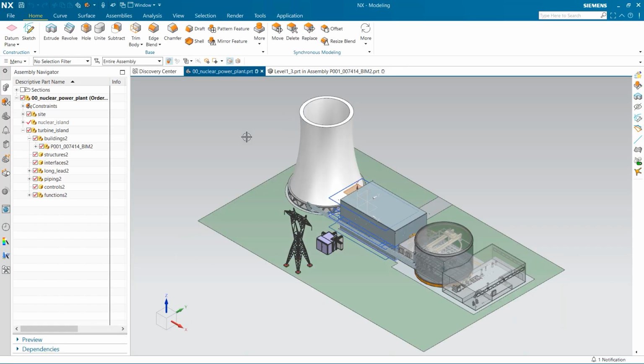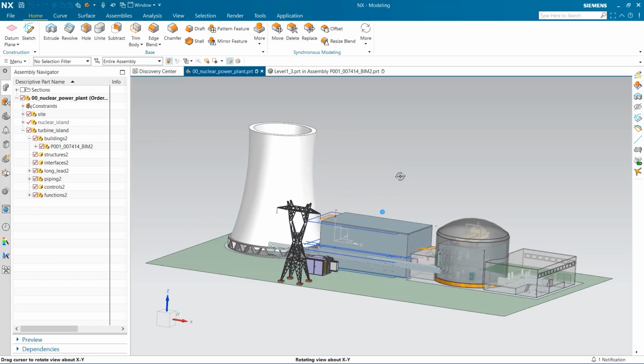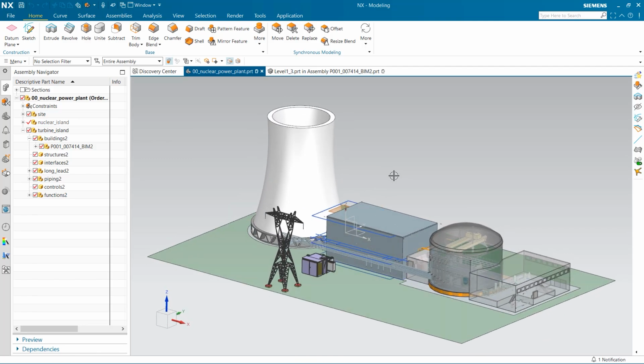You can see how easy it was to make a building using BIM. You saw me create levels of varying heights and then make a sketch on the bottommost one. You saw me build walls referencing this sketch, and I then made interior walls using grid lines. I was then able to modify all these things and have the model update in the power plant assembly. Finally, you saw me finish up the building by adding a roof.